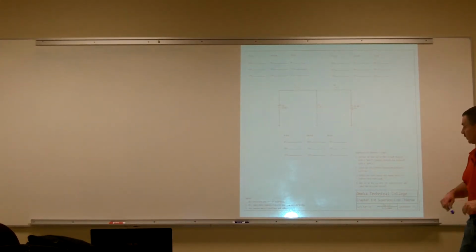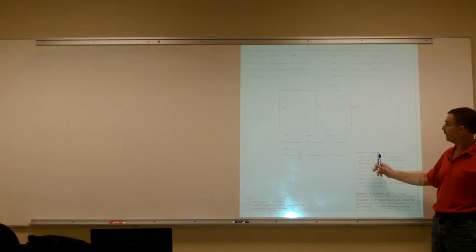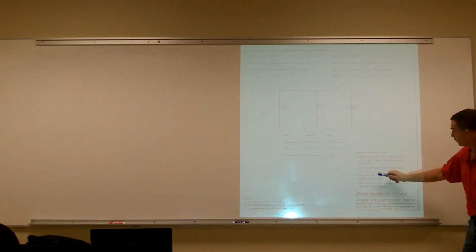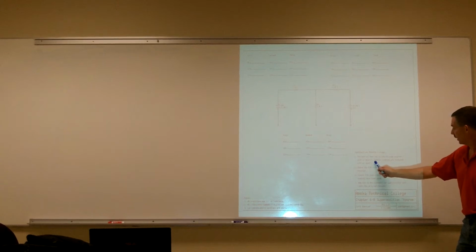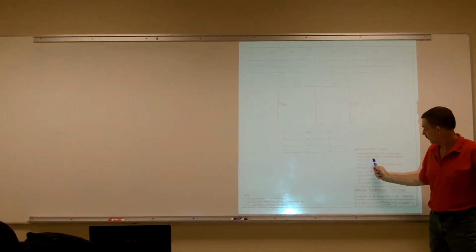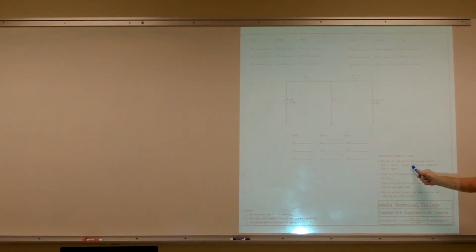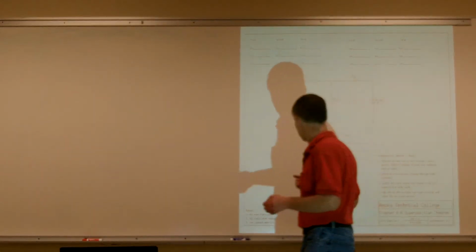So what it says is to replace all but one of the voltage sources with a short. Current sources are replaced with an open. Okay, we can have 2 different types of sources. All our sources that we use out in our labs are all voltage sources. When we get into solid state, we're going to talk about current sources coming up. That's where it remains a constant current, no matter what's going on with the load. Here, we have voltage sources that, no matter what I do to the load, always maintain a pretty specific voltage unless we really load the thing down. Current sources maintain a certain current going through the load, no matter what the resistance is.